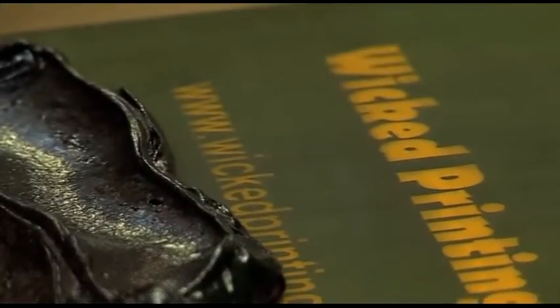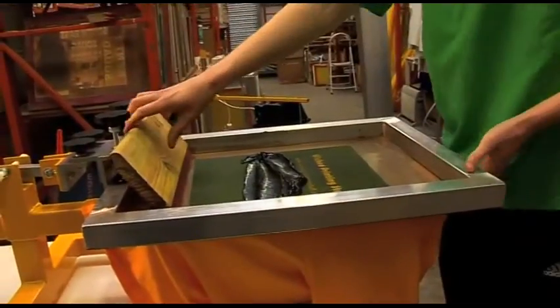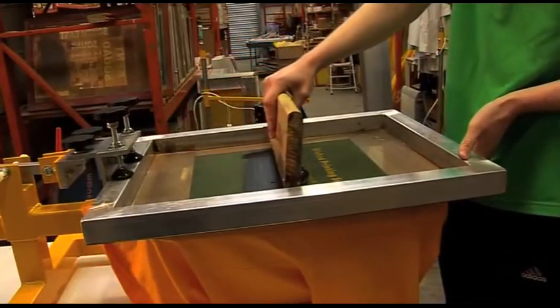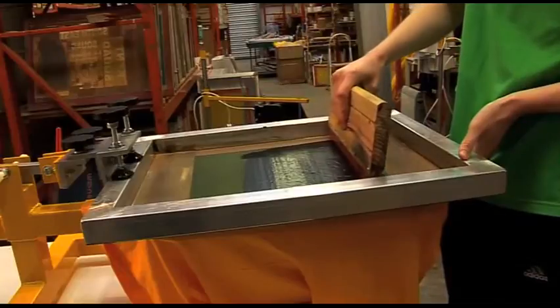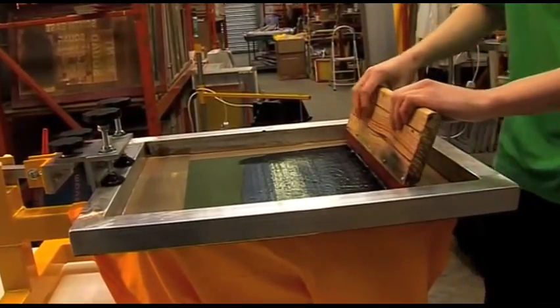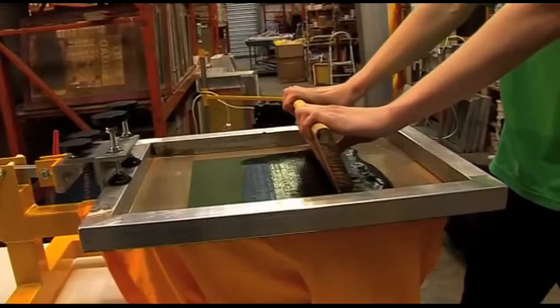Today our printer will be using a D-cut squeegee, as our design does not have any intricate detail and we want to put a nice deposit of ink. Lift your screen roughly an inch above your platen and flood your image. Lower your screen. It is advised to hold your squeegee with both hands with a medium to hard grip. Tilt your squeegee at 15 degrees away from you and draw the squeegee firmly across the screen. If preferred, you can also draw the squeegee towards you.